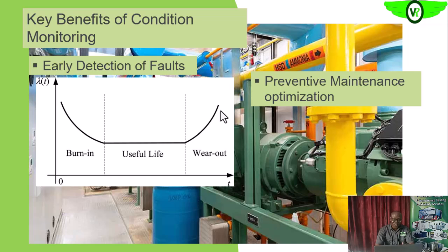Okay, there are some components of the equipment that you know have little effect on the operations of that equipment or of the process, or whose cost of replacement is minimal. This effect is minimal, and it does not affect the safety of your process or of your plant. Okay, you can allow such equipment to run to failure.